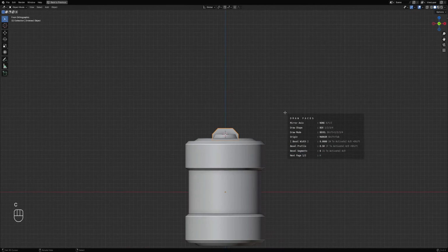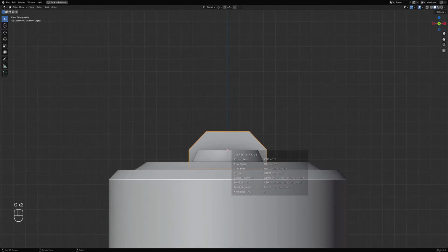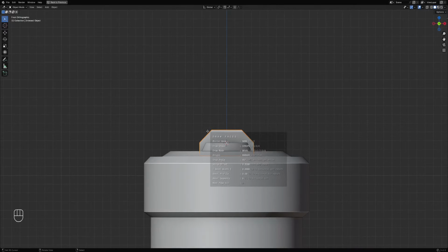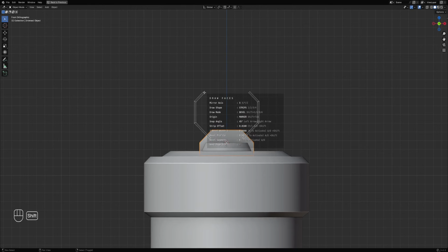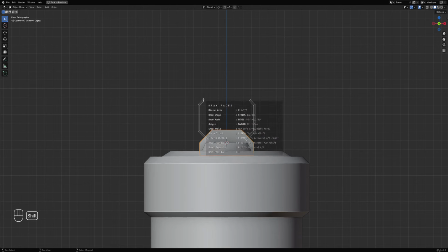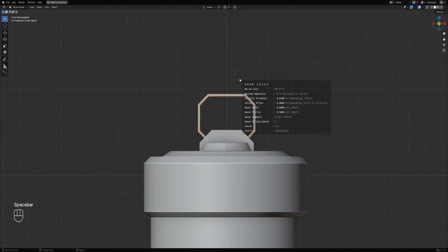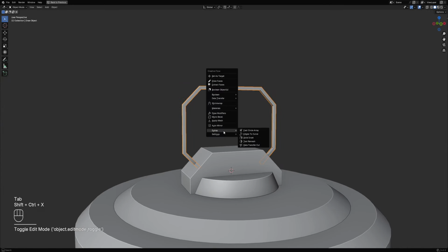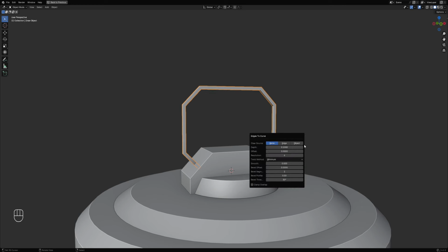Draw faces, press C on open space to get the X marker on the center of the object. And we're going to use that as the distance in which to place the draw object based on the view angle. Okay, press 4 for strips and press X to preview the X mirror. Create a line there or edge loop. And then extras with that edge selected, edges to curve and get rid of the object.